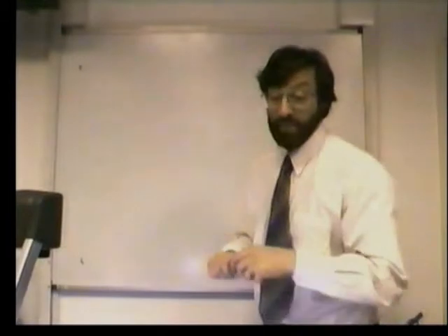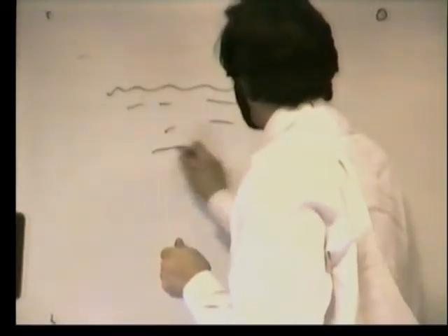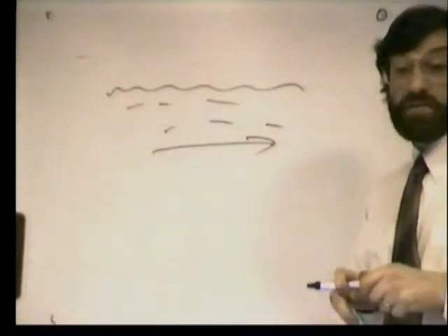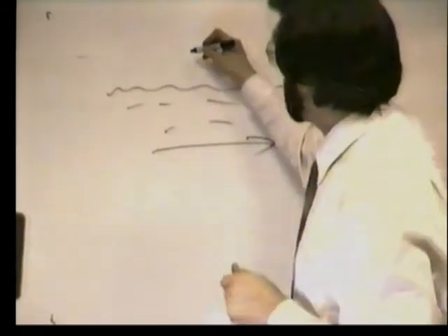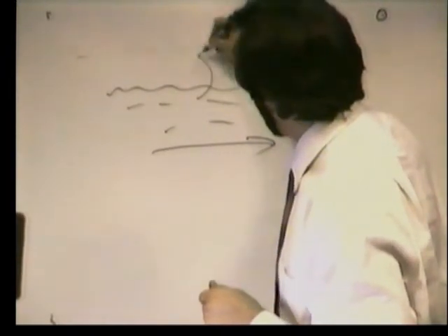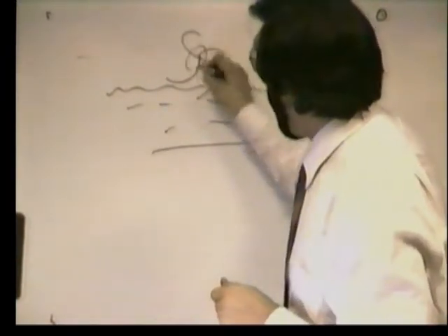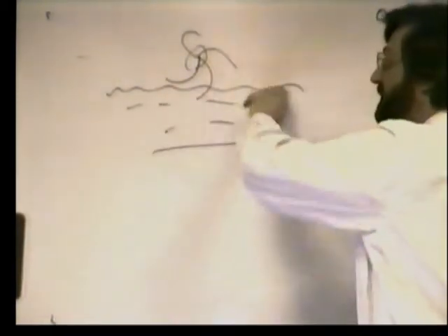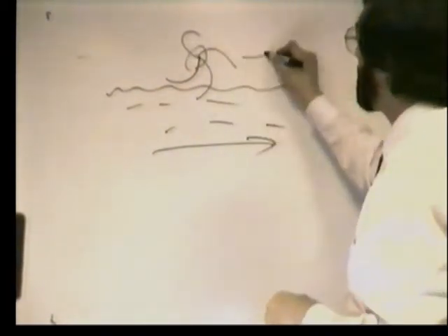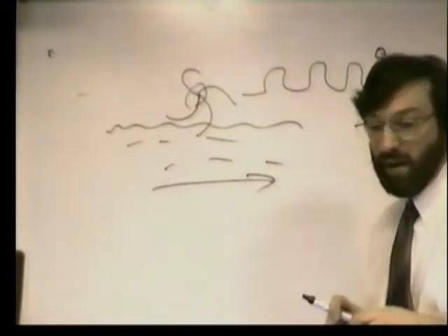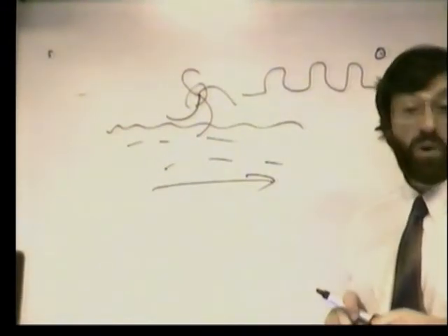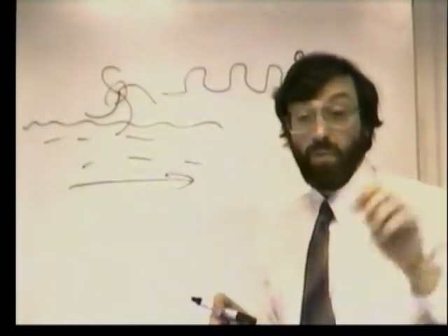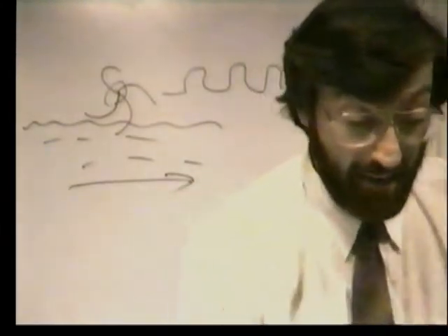So let's consider a very, very simple flow meter. Let's assume there's some water flowing along. How can we measure the flow rate of that water? Well, if we were to put a very simple turbine, a paddle wheel there, as the water flows it rotates the paddle, and we will get a pulse train coming out that is directly proportional to the rate of flow of water. I've actually got a flow meter here.